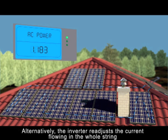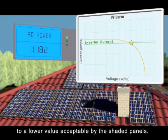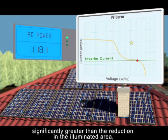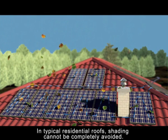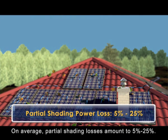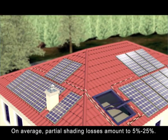Alternatively, the inverter readjusts the current flowing in the whole string to a lower value acceptable by shaded panels. In either case, power loss in partially shaded arrays is significantly greater than the reduction in the illuminated area, because power output is also lost by non-shaded cells and panels. In typical residential roofs, shading cannot be completely avoided. On average, partial shading losses amount to between 5 and 25%.